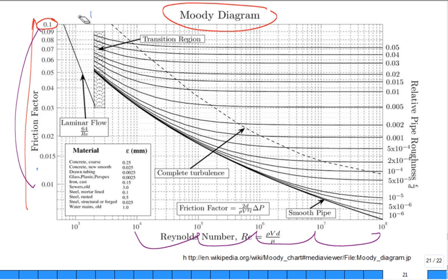All right. So right away, if you're ever doing any work and somebody says, I think I calculated the friction factor to be 4.3. What are you going to say to that? You got a friction factor of 4.3? Really? What's the maximum number on the Moody diagram right here? 0.1. You should be skeptical of anything over 0.1. Or you say, are you sure it's not maybe 0.043? Are you off by 100?